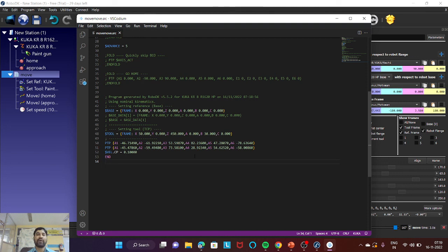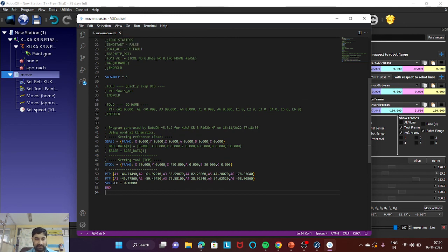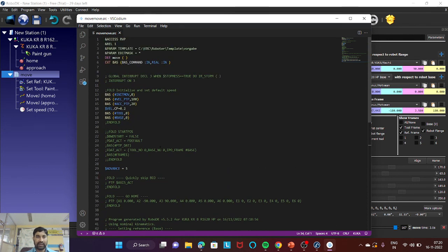Whatever movement you want, you can consider all the movements, and while production things are going on, you can limit the movement of the robot here, and you can test here without any prototype. And if you feel it is safe, then you can directly move this program to the robotic software. If you want to change anything, it is very easy to change here. You can change the coordinates here, easily change the coordinates, and you can re-enter them. It will take them.